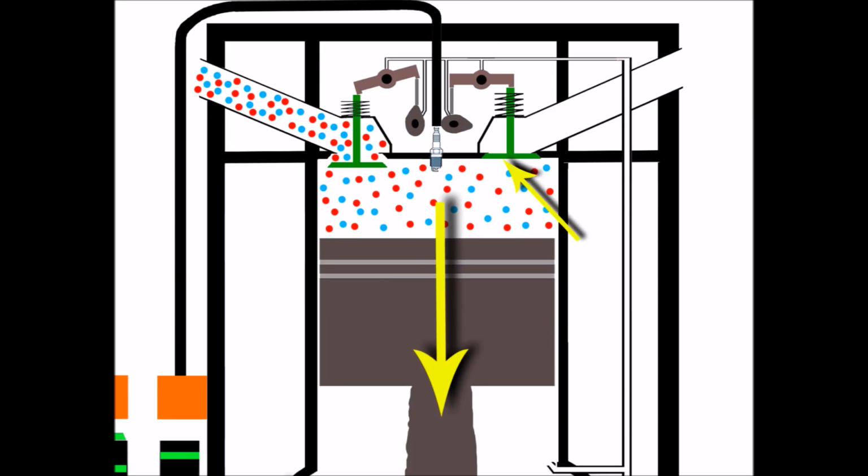So there we are, we can see a little better now, and we can see there that the exhaust valve is closed and the inlet valve is open. And we can now better see these components here. These are called rocker arms. And one thing we'll notice is that this rocker arm is tilted, and that's because of the camshaft I mentioned earlier. If we look now, compared to the exhaust camshaft here, where the uppermost peak, the largest peak, is facing outwards to the side, the one here on the inlet has rotated and is now facing upwards.